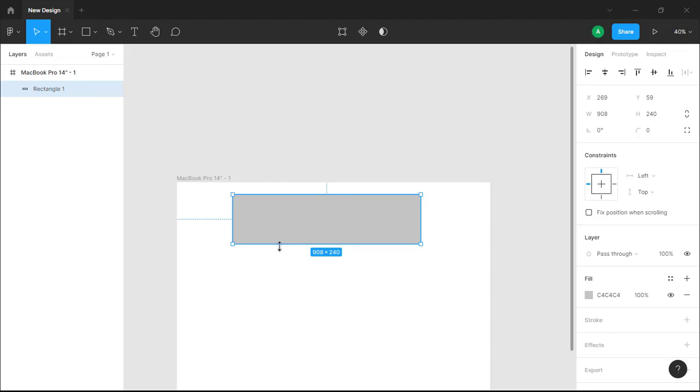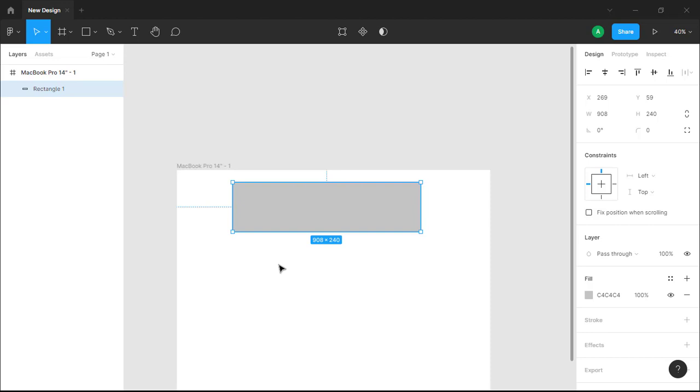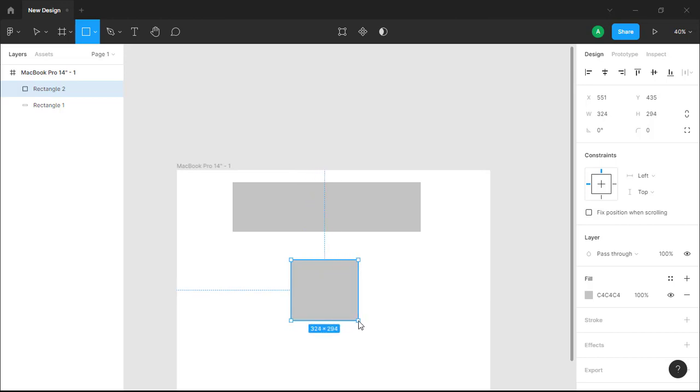Let's say you want to create a square. So I'll pick the rectangle tool. I'll try creating a square. If you notice, I'm finding it very hard to just get a perfect square. For you to do that, you can hold the Shift while you drag. You see, if you hold the Shift on your keyboard, then you can drag in and then drag out to get a perfect square. So that is how to create a square.